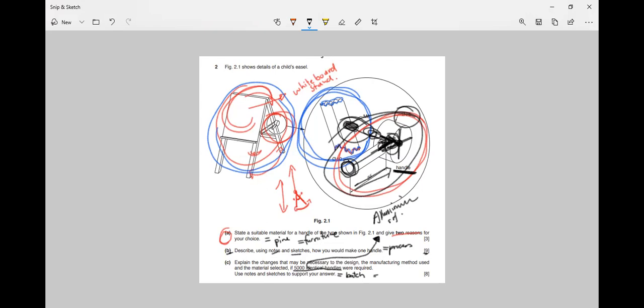That's true. Okay, so for me, it would be something like quality. How do you maintain the quality? Because now you've got identical things, yes, but if you know batch production, you know that they're all connected to each other with a little strand of plastic normally, and you have to break that off. It always leaves a little bit of sharp plastic edge that needs to be sanded down. So quality is always an issue when it comes to batch production and mass manufacture, because that's basically what it is. Yeah. Okay.